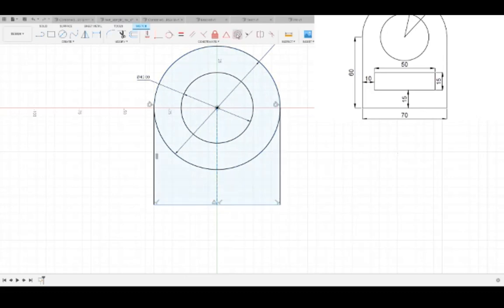So we have that. We have concentric, which means that both two circles or arcs hold the same center. That's obviously pretty self-explanatory. Symmetry means that you can select one object on one side, one object on the other, and then a symmetry line or plane. That now means that if you don't have a midpoint dimension, or things are unique, the lines of your two selected elements will be the same relative to that midpoint. And then you have curvature, which actually I don't fully know. I've never seen curvature before. Presumably that would generate curvature on a static sketch or something else.